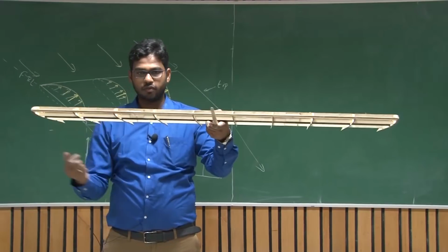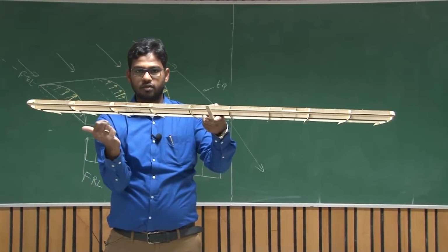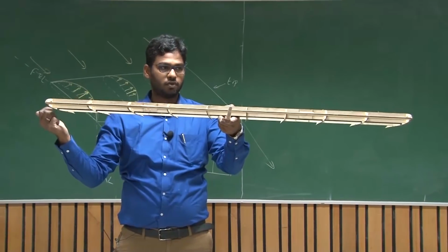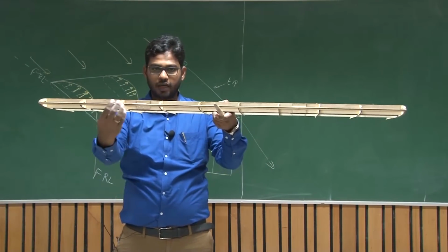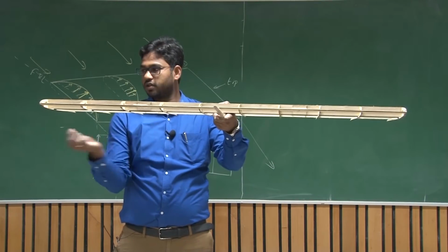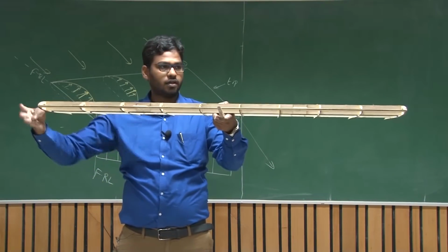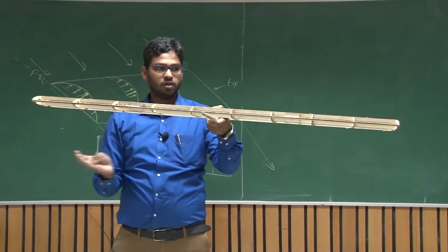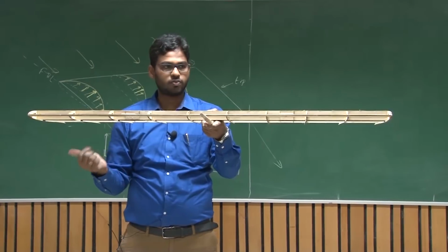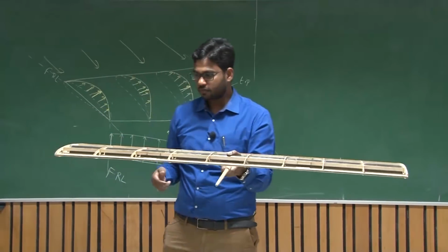So this curling will actually affect the span-wise flow. It will actually induce the span-wise flow. Ideally, the flow has to be along the chord, right? But this curling, due to the finiteness of a finite wing, will induce a span-wise component of velocity to this flow, right?